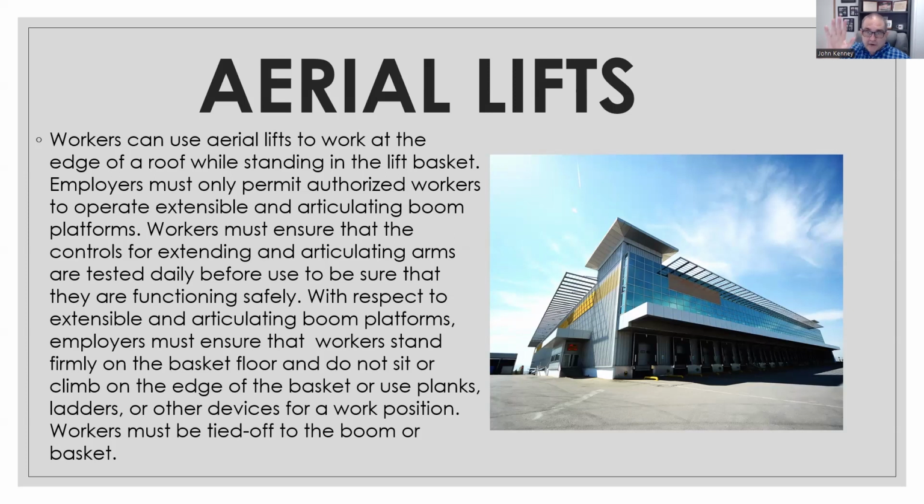You cannot put a ladder and extend up to work out of. Can't put a platform across the top of it to get up to the extra height. They have to be used for what they're intended. And again, everyone has to be trained properly and have a sign off on your training.